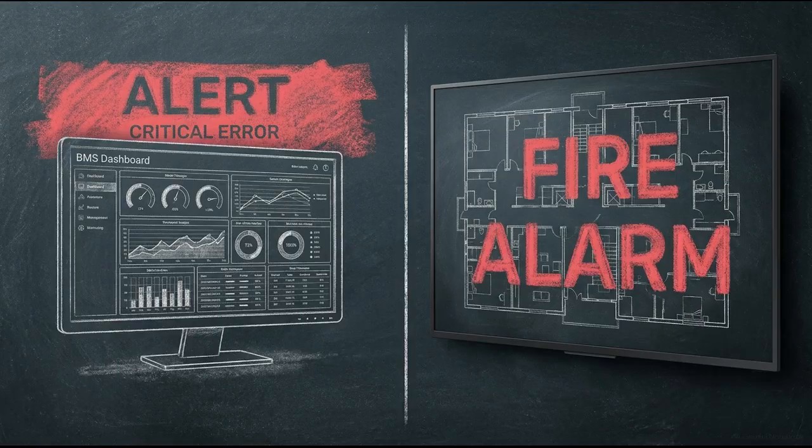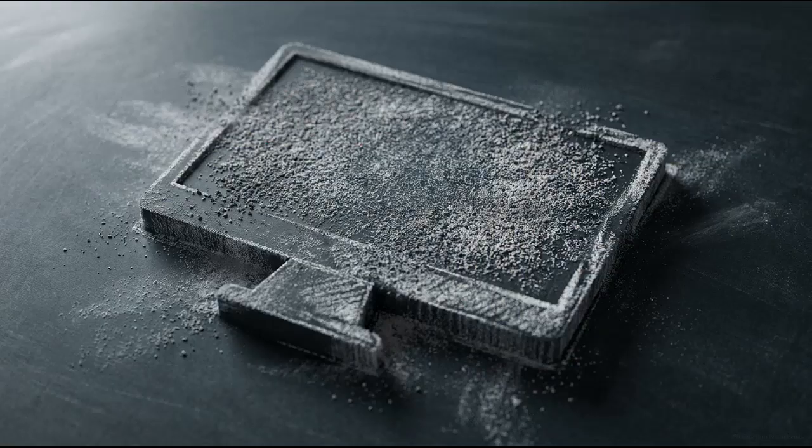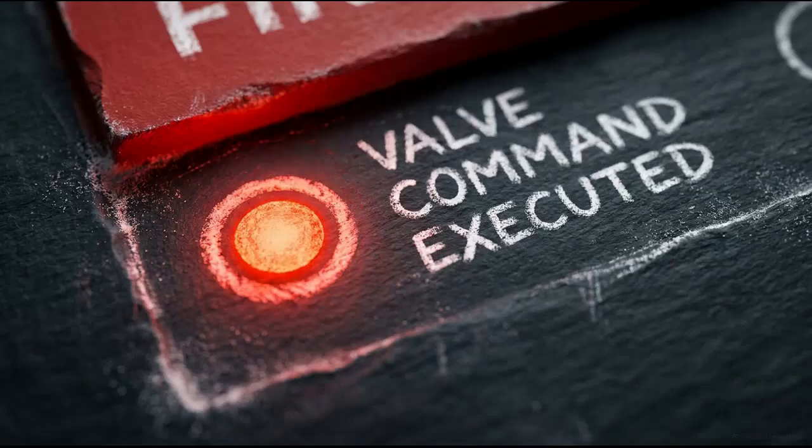Building management systems and security operations centers receive status updates, but they are strictly monitor-only platforms. Network failure or a stalled HMI screen on a remote supervisory computer must never defeat the local releasing autonomy. The fire panel retains absolute physical control over the abort logic and valve command.